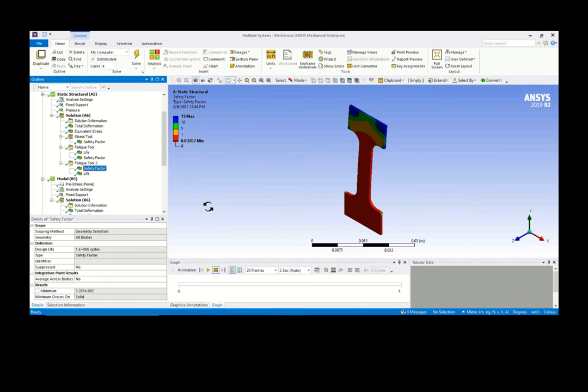At 22 cycles, this whole thing will break. All right, so that is the thing that I want to highlight and want you to consider in your fatigue analysis. We think it is more appropriate if you take into consideration the effect of frequencies.